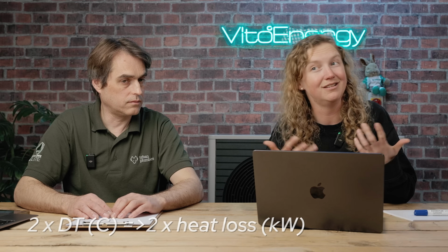So when we talk about a single number for a building, what we're actually talking about is, at my design outdoor temperature, what is the heat loss of the building? It's not like a fixed value that building is always losing heat at. What is the design outdoor temperature? The design outdoor temperature is the worst case outdoor temperature for which you're designing your heating system. And to that temperature, we're going to be sizing our heat pumps or boilers or radiators, right?